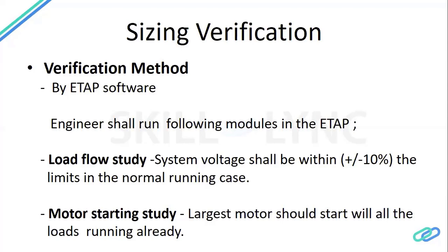We will simulate the complete single line diagram in the ETAP, and we will run the load flow study, and we will see what the voltage levels are on the switchgear or on the motor. And generally, the voltage should be within plus minus 10%. If it is in that limit, then the load flow study is okay.